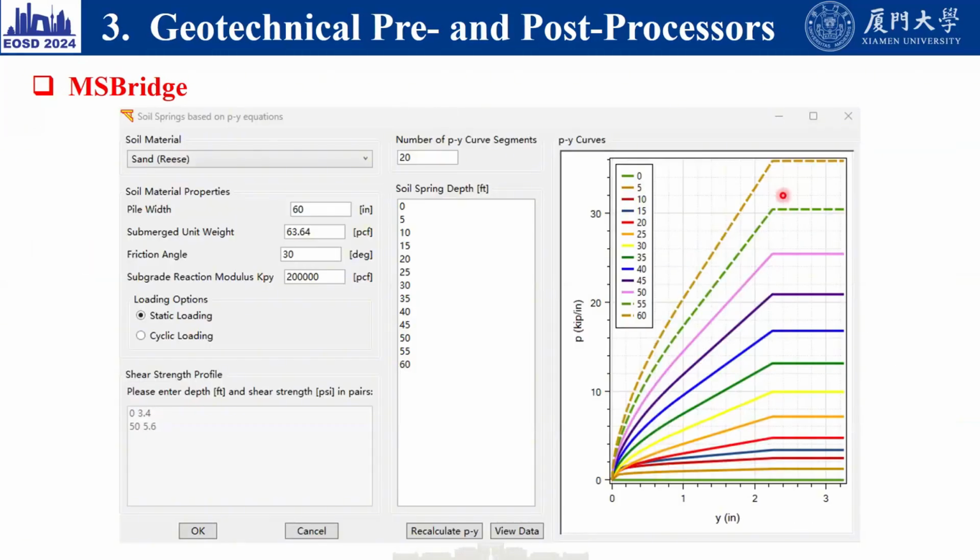So in this software, we can also do PBE analysis. Like I said, PBE, performance-based earthquake engineering, is becoming more and more popular because it will avoid the uncertainty in modeling, right? If you just run one single motion, there are many uncertainties related to the material property, the motion characteristics, and many other parameters. So that's why people do performance-based earthquake engineering right now.